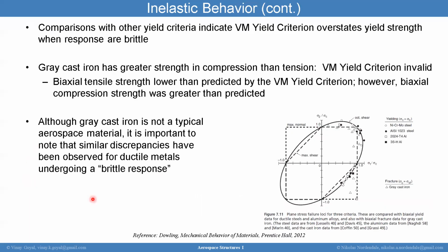So here is some test data that goes way back, showing in a 2D stress space the normalized stresses at yield. The solid line is the von Mises ellipse, taken as a slice in the sigma 1, sigma 2 plane. The dotted line, that's a trapezoid inside of the ellipse, is your Tresca failure criterion, or your max shear stress criterion. And then of course your max normal stress is the dotted line that turns it into a square.